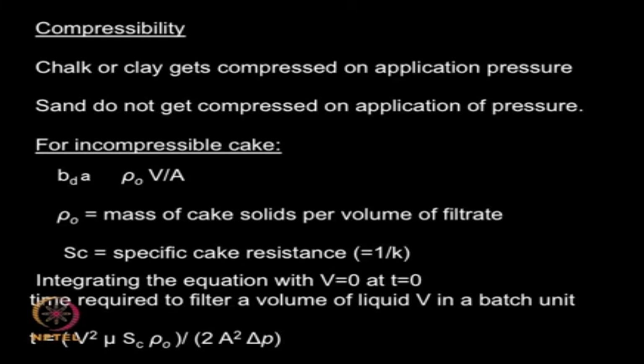So I can do both, I can use it as a design equation or I can use it as a simulation equation, and this is a very interesting equation because by assuming several conditions we got a very simple equation, and it is very useful to make use of this equation for calculating the time of filtration or area required for the entire filtration process.